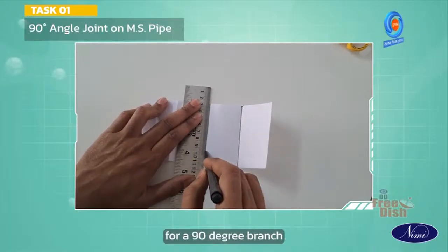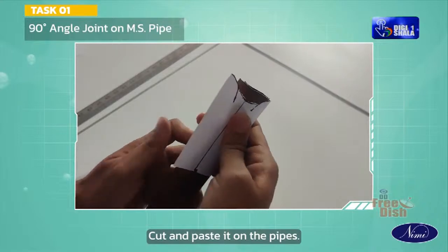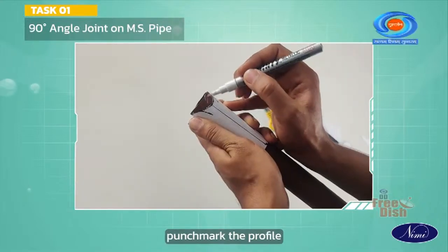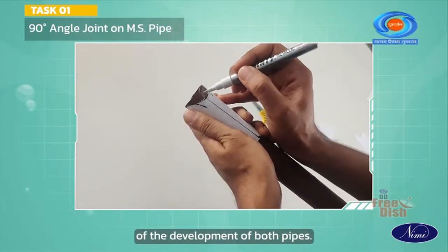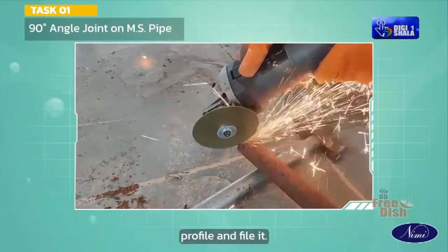Prepare the development for a 90-degree branch on a drawing sheet. Cut and paste it on the pipes. Punch mark the profile of the development of both pipes. Cut the branch pipe along the punched mark profile and file it.